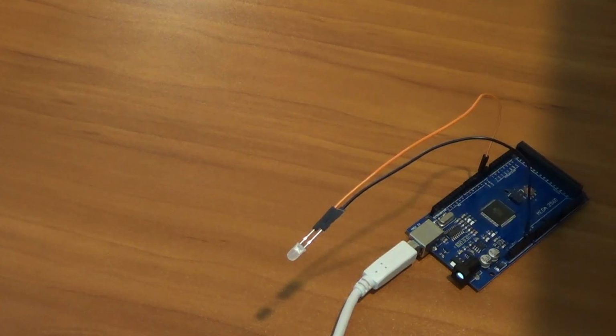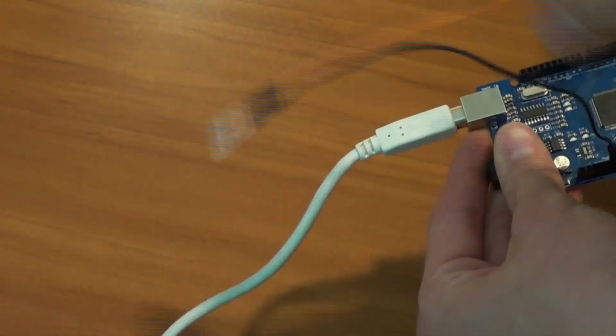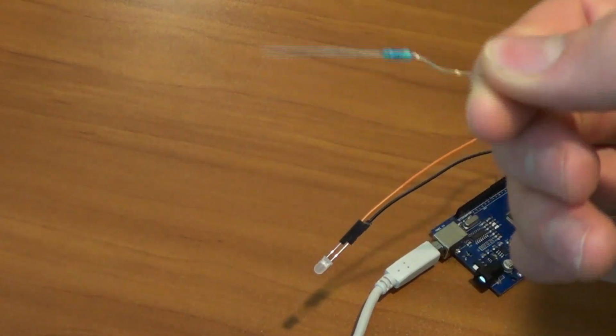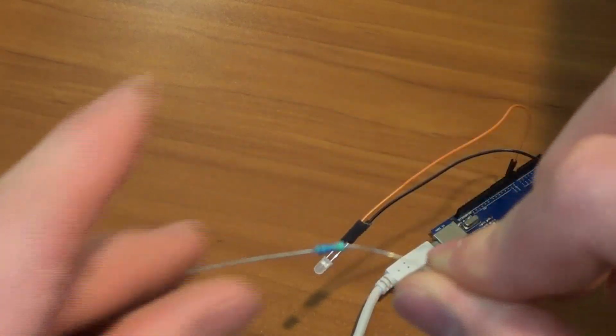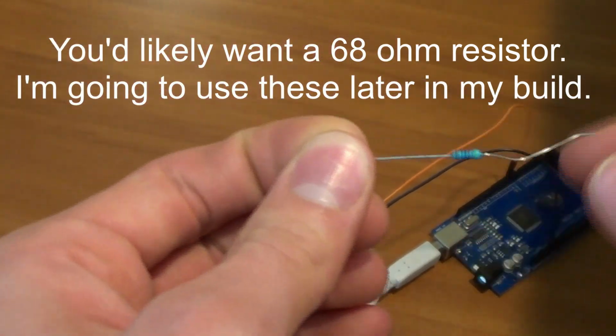If we were to turn this on, which I'm not because I've done that before, you'll notice that there are 5 volts basically coming from the Arduino into the circuit and frying up the LED. If you want to potentially start a small restaurant in the LED, that is fine, but we are going for a lifespan, so we are going to use a resistor. This resistor is a 430 ohms resistor, but do not use this one. I'm using it shortly for the demonstration. It has too much resistance and will make the light basically pretty dim.